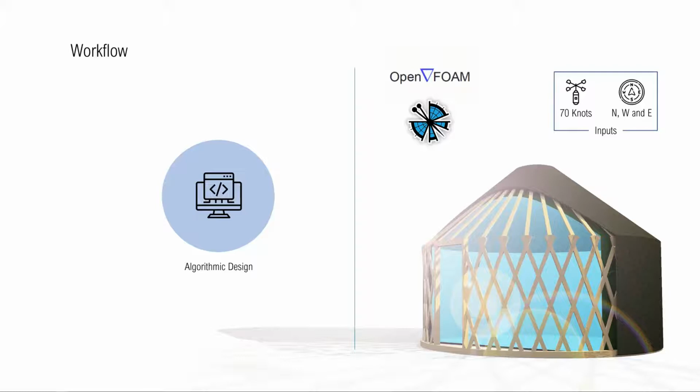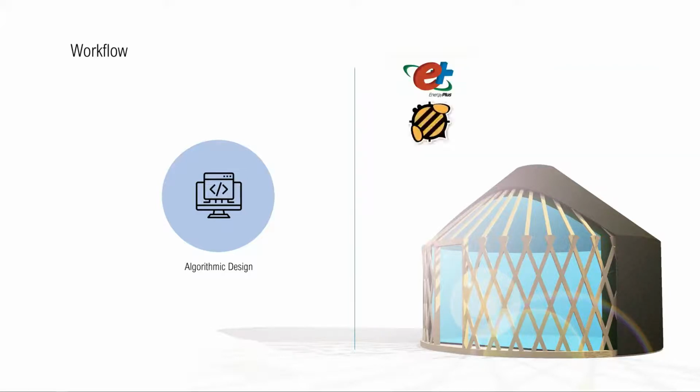For the comfort analysis we used EnergyPlus with Honeybee, and the shelter geometry, its material properties, and weather data gathered by the data loggers as inputs. Lighting and occupancy schedules were switched off due to the existing conditions of this shelter.